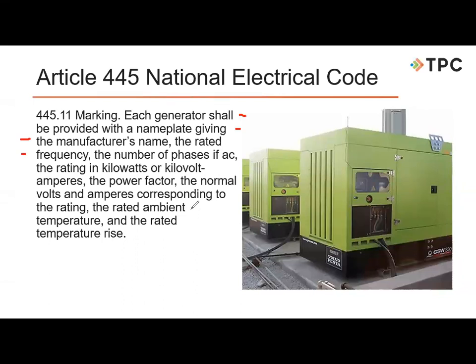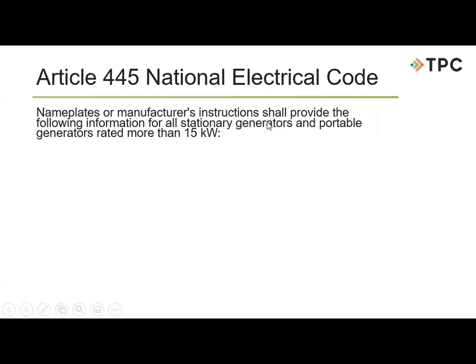So also we can see what ambient temperature the generator is going to be installed in and the rated temperature rise. And when they talk about temperature rise, that is how much that the internal stator windings can increase in temperature over the ambient. So we're going to take a look at all those different factors coming up here. Now, this information is regardless of size. It does not matter how large the generator is, how small the generator is. All this information would have to be on any size generator.